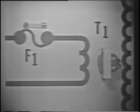Now notice the fuse on the trainer. If a short circuit develops somewhere in the rectifier, the resultant excess current drain will probably blow the fuse. Actually, that's the purpose of the fuse. It's designed to be the weakest link in the circuit, to burn open if excess current suddenly flows through it. Now when it opens, it stops all current flow in the circuit, thus protecting all the more expensive components. Now an open fuse produces a no output symptom, but remember, if you find a blown fuse, look for the short circuit that caused it to burn open before you replace it.